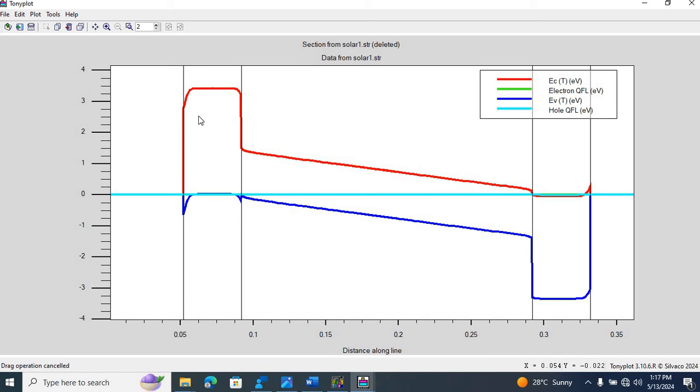On this side we have the indium tin oxide layer, and indium tin oxide over here is a contact. Then this one over here corresponds to the nickel oxide film, which is p-type, since the Fermi energy level is close to the valence band. Similarly, this layer on the right is zinc oxide, which is n-type, as is obvious from the fact that the Fermi energy level here is close to the conduction energy level.